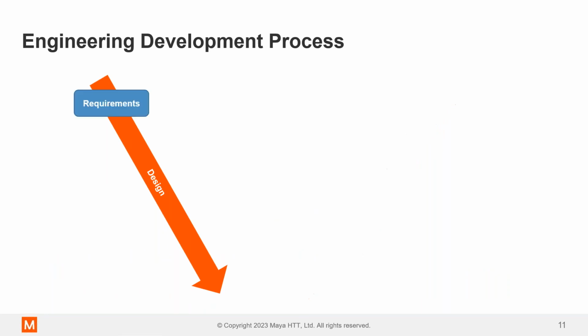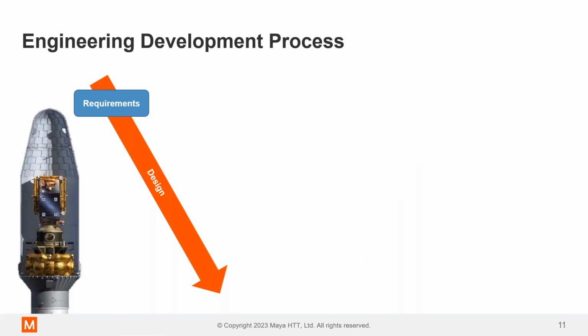But if we look at the engineering development process, it's generally going to start with requirements. And I'll do sort of a space-based example here, but this applies to many industries. If you have a spacecraft sitting inside a fairing, like I mentioned before, you're going to get a lot of vibrations transmitted into the base of the spacecraft where it connects. And additionally, you will get many vibrations due to acoustics that are reverberating off of the panels and hitting these big panels on the satellite, on the spacecraft itself. And that's causing vibrations, random vibrations, to shake all the components sitting on those panels.